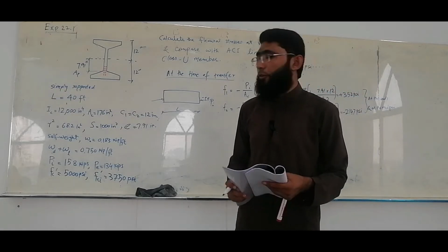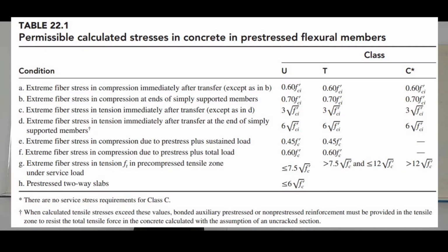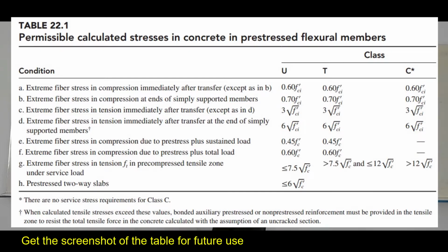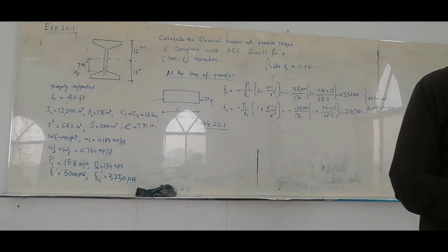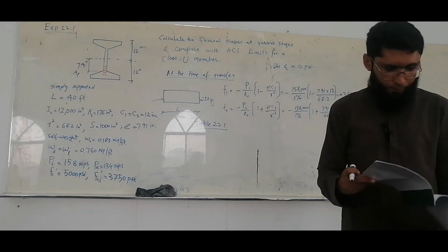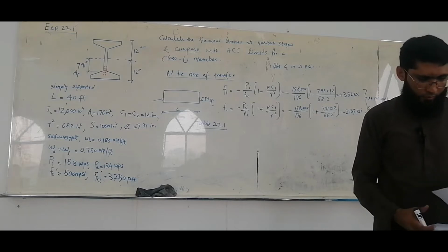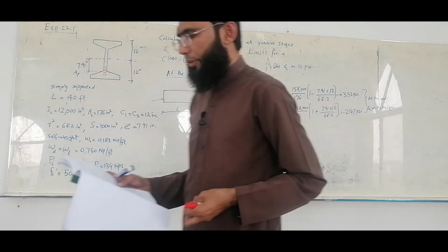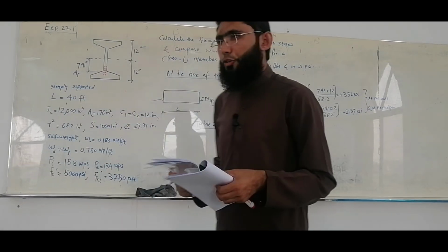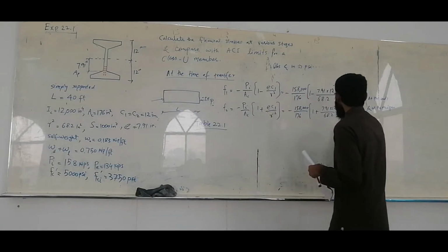Now, if you go to table 22.1 of this book, Design of Concrete Structures by Nilson, Permissible calculated stresses in concrete and pre-stressed flexural members. You need to compare these.